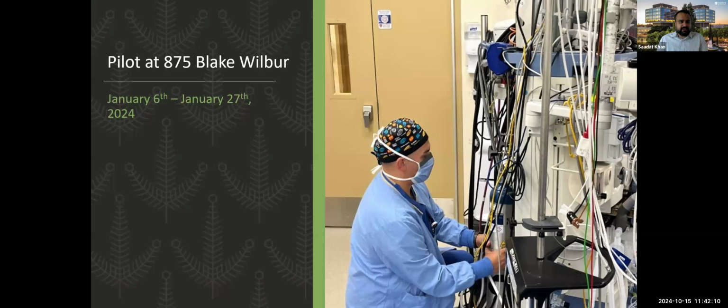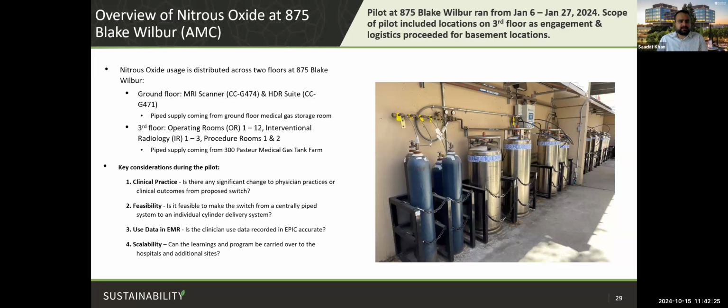And so with that, I'll expand a little bit more into the pilot at 875 Blake Wilbur and show some more of our results, which happened from January 6th through January 27th, and how this all came into place. As a background, nitrous oxide usage is distributed across 2 floors at 875 Blake Wilbur, which is the ambulatory surgical center. On the ground floor, we have an MRI scanner and an HDR suite with piped supply coming from a ground floor medical gas storage room, and that is using 8 cylinders.